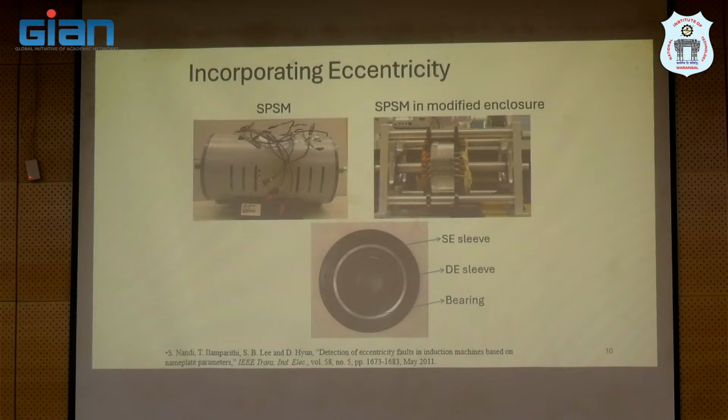Okay? So that is something for you to keep in mind, because our intention is mostly on propulsion motors used in electric vehicles. This type of synchronous motor is also being used in electric vehicles. For example, some European car manufacturers use DC field excited synchronous motors just because they want to avoid rare earth magnets.